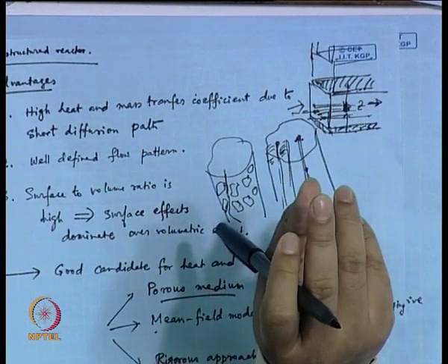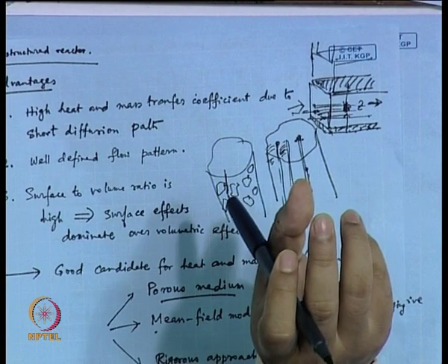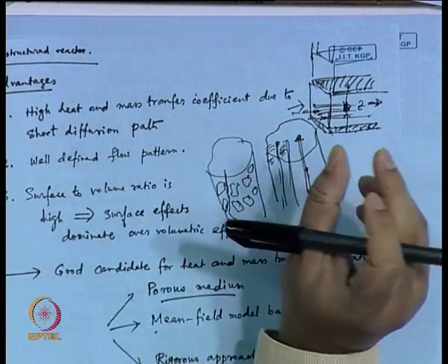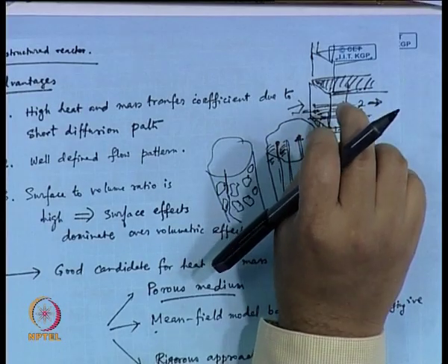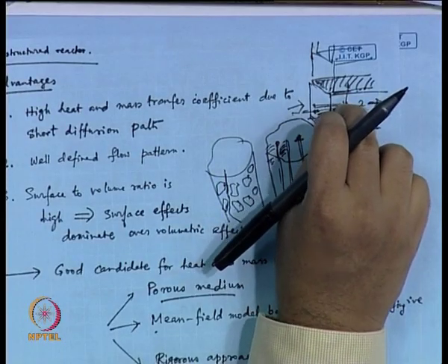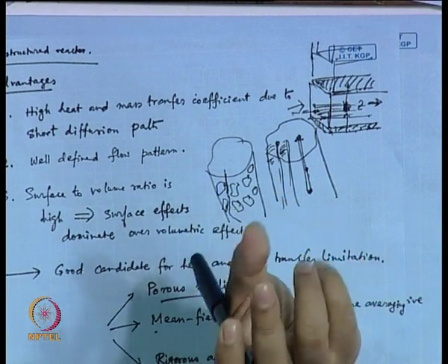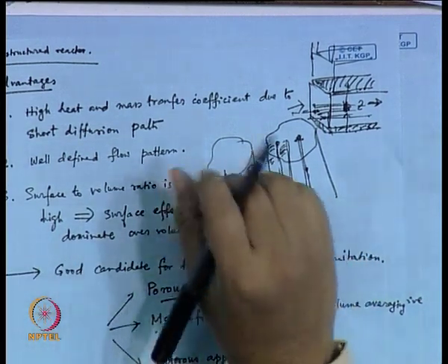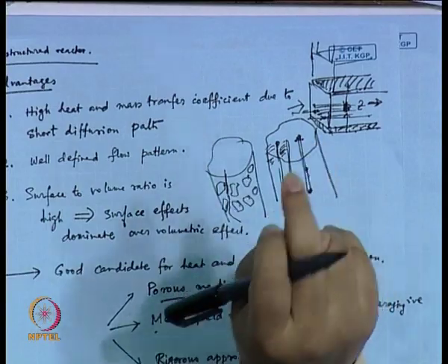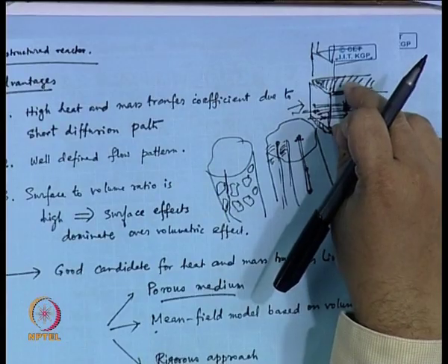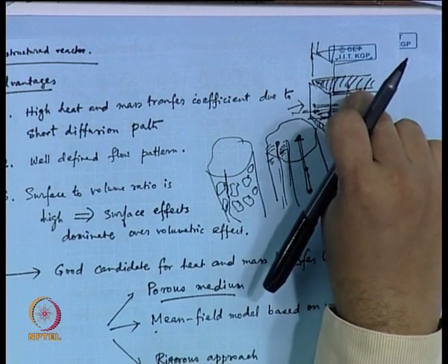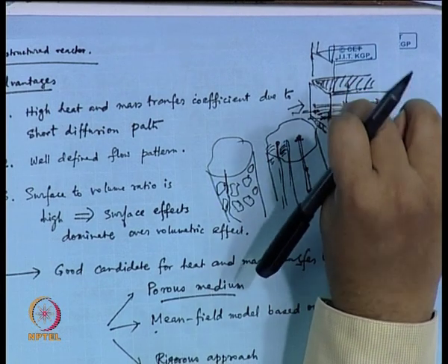Now, you have that window you are creating, and so you are producing side reactions, you are getting into other things. Now, the reason you are choosing a microstructured reactor is that this temperature, that delta T, you can minimize. When we are talking about 1000, we are talking about 995 to 1005. That window is going to be smaller in a microstructured reactor.